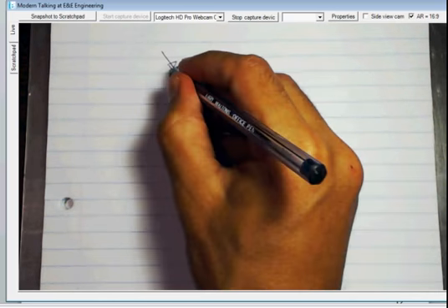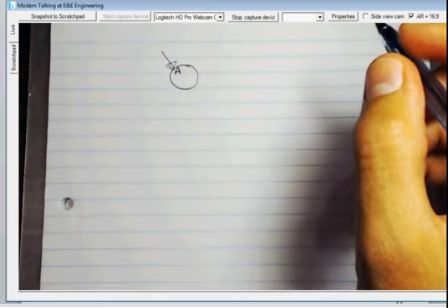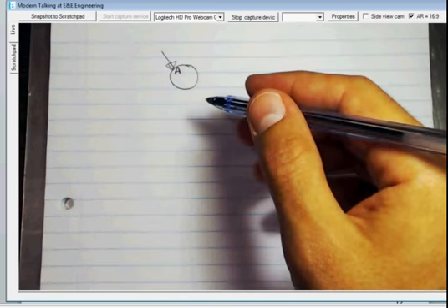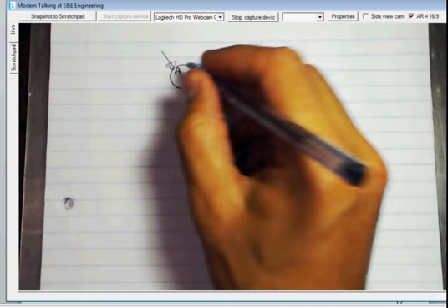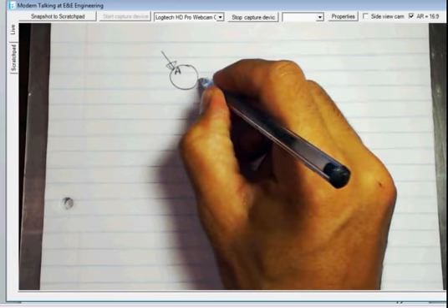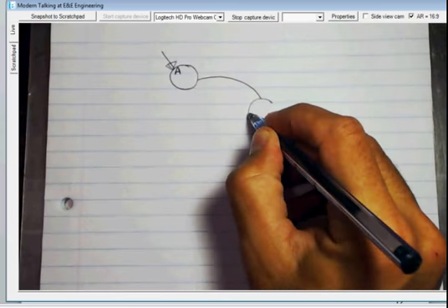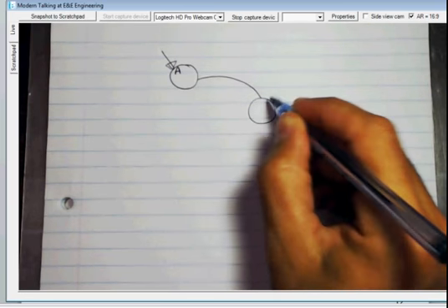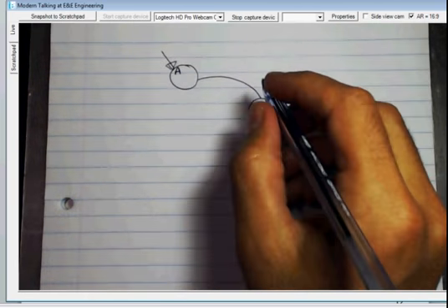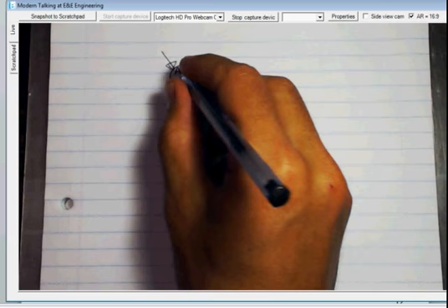And I don't mean it's being reset. I mean it has been reset. Okay, so that's the first state that we enter into. Let's just label it A. So we've not received anything. Then what I typically do is I say let's follow the normal sequence and see how many states we have. So state A is we've received nothing.